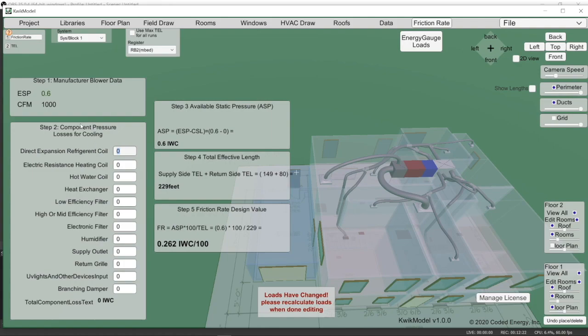And usually out of the 0.6, if you go to look, you would have to look at the actual coil itself, and the manufacturer will give you a table that says at this many CFM this coil has this much static pressure drop. Okay, and you want something that's around the 0.25 range. Lower is better. You can always upsize your coil. If you have a 2.5 ton system, you can put a 3.5 or maybe even a 4-ton coil on that thing, as long as there's an AHRI rating for that combination.